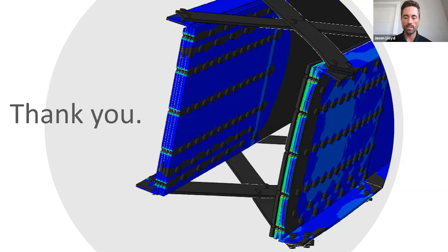And what we found in the built-up construction is that it was very difficult, because as that crack developed in one of those components, it becomes more compliant relative to the other ones that are connected to it through rivets or bolts. And as that becomes more compliant, it sheds load naturally to a stiffer adjacent component. And so that takes some of the demand away from that crack tip. And so that critical length is no longer as critical as we might be calculating.